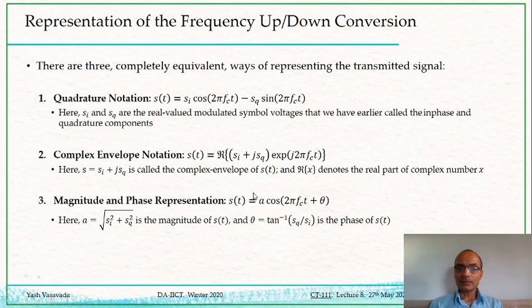Okay, one thing that I am reminded of, I should mention, the reason for the names of those digital modulation schemes, phase shift keying or quadrature amplitude modulation, amplitude shift keying, etc., is because of this magnitude and phase representation. For phase shift keying, this A remains constant and this theta keeps on changing for different symbols.